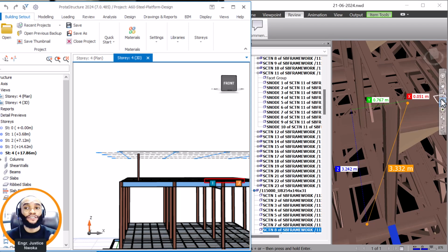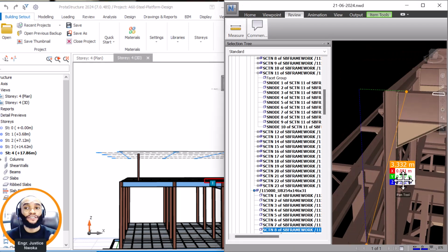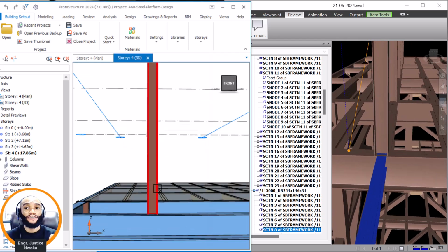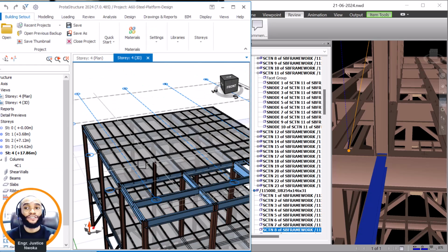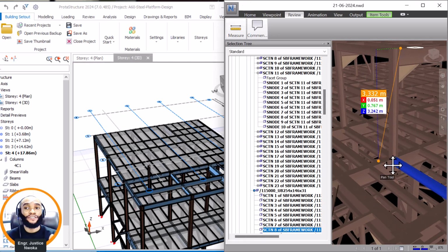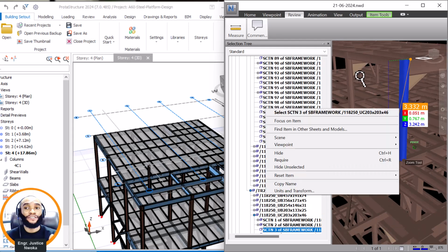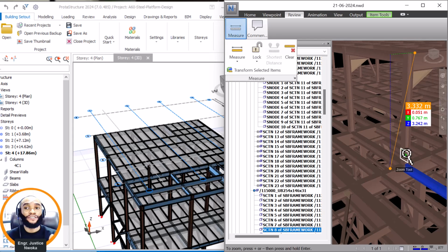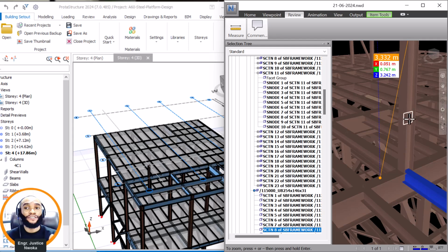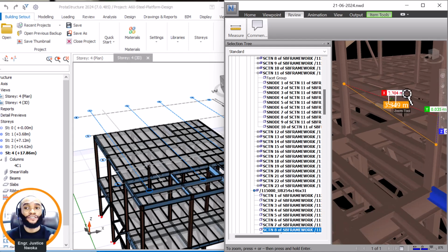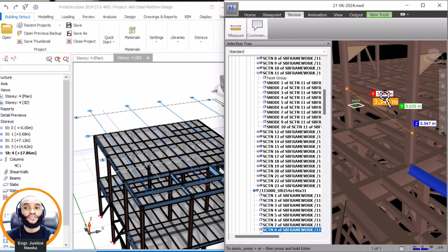Now let's look at how the column is oriented. So we are seeing these two flange width now, which is also what we have here. All right, seeing these two flange thickness, that's fine. So the next thing we have now is to know the distance between this stanchion here, which is a column, and this steel column here too. Okay, that's fine. So we're going to measure that too. Measure this now, center to center, by coming here, clicking on this center here, and then transferring this here. Let's see. That will have what? The X here is 3304, so actually 3305.